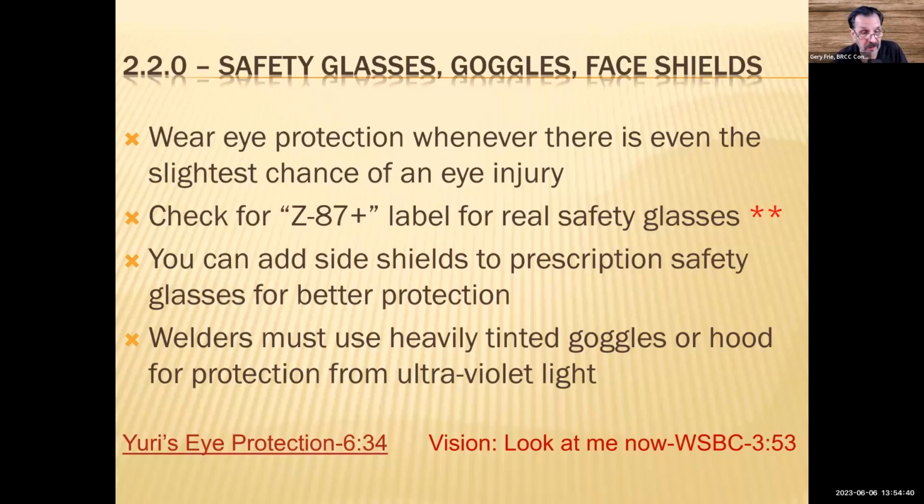Welders use very heavily tinted goggles or a hood for protection against extreme light, and particularly the ultraviolet light, but also the infrared light and other intense light. But the ultraviolet light is probably the most important hazard that you protect against.